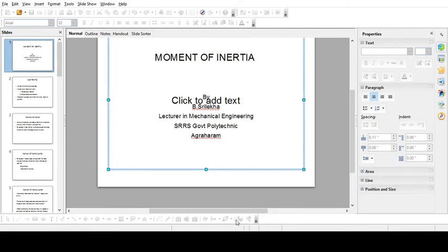Next, for each standard section, you need to find IGX, meaning moment of inertia about their own centroidal x-axis, and IGY, moment of inertia about their centroidal y-axis, for each standard section. Next, after that, we'll take the area and the distance square, that is area into distance square along the y-axis.